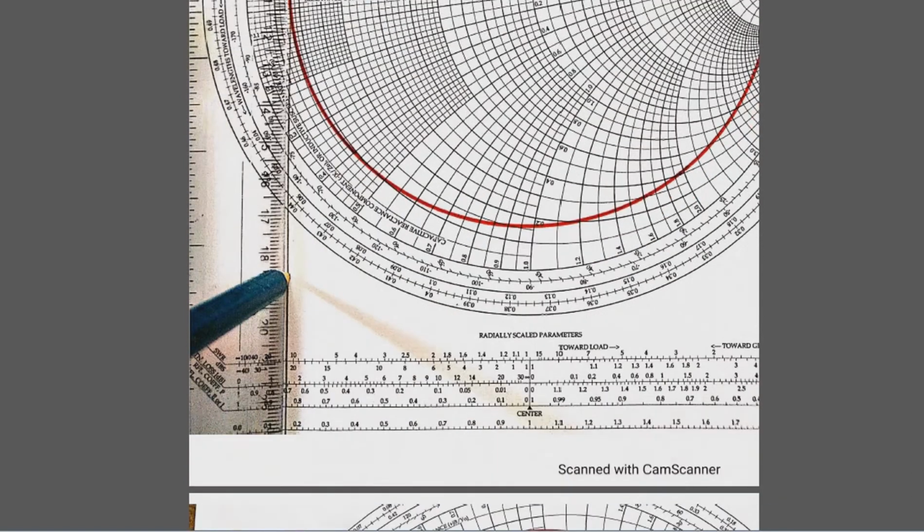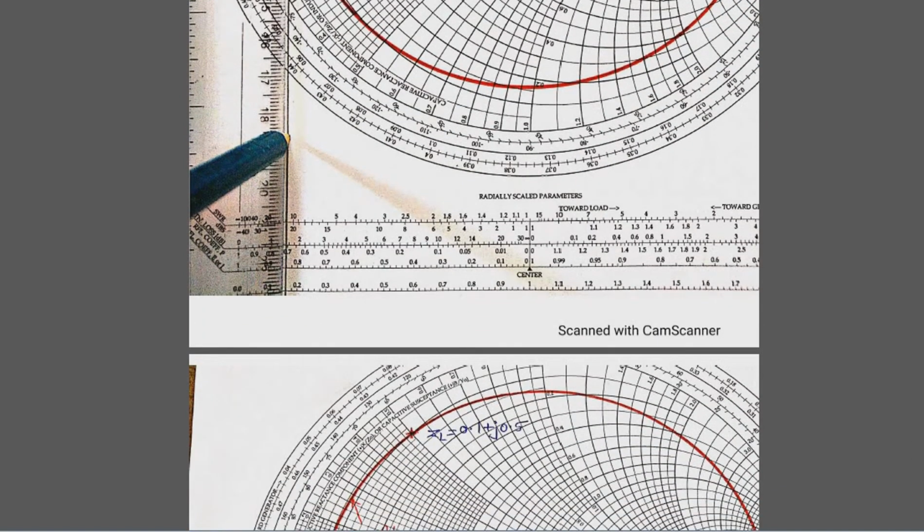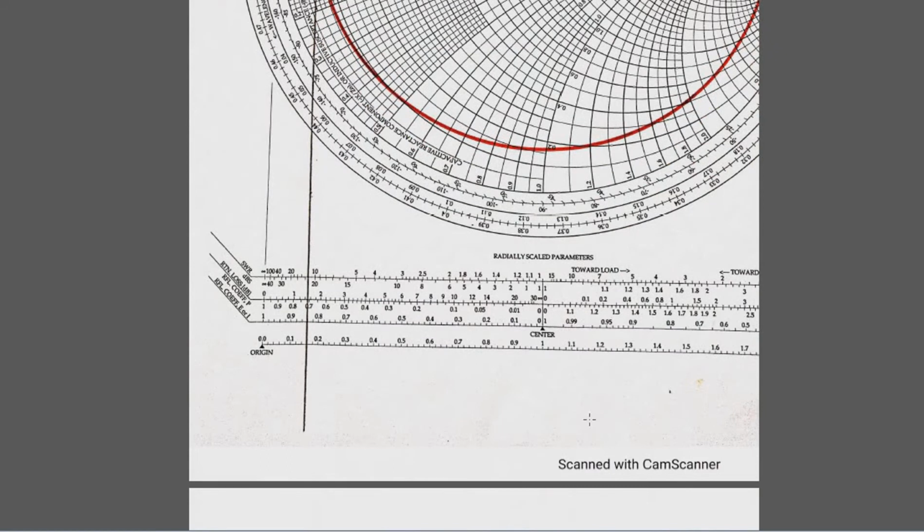Now I am going to find out that this is the SWR in dBs. The third scale is nothing but the reflection coefficient. This is SWR. This one is going to be the reflection coefficient. I am going to mark those values. This is the line whatever I had drawn here with a pencil. Then for the SWR, I am going to point this out with a magnified scale in the next.